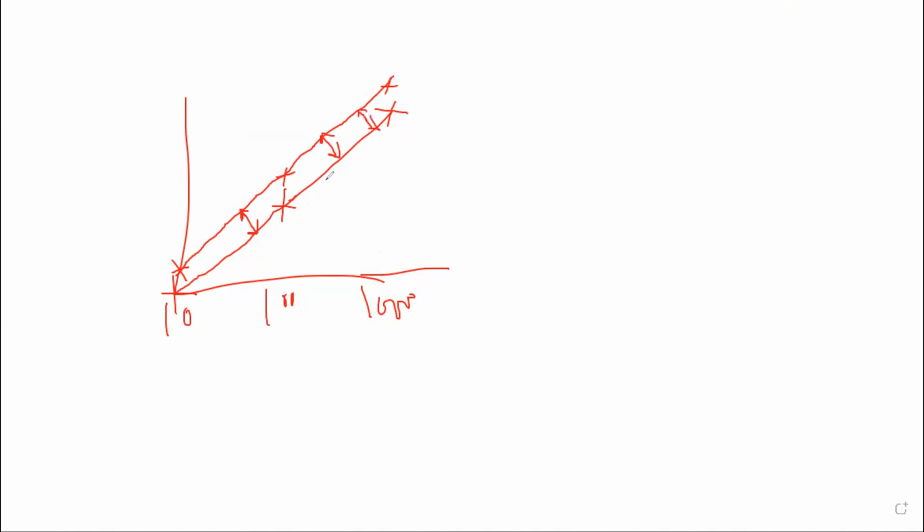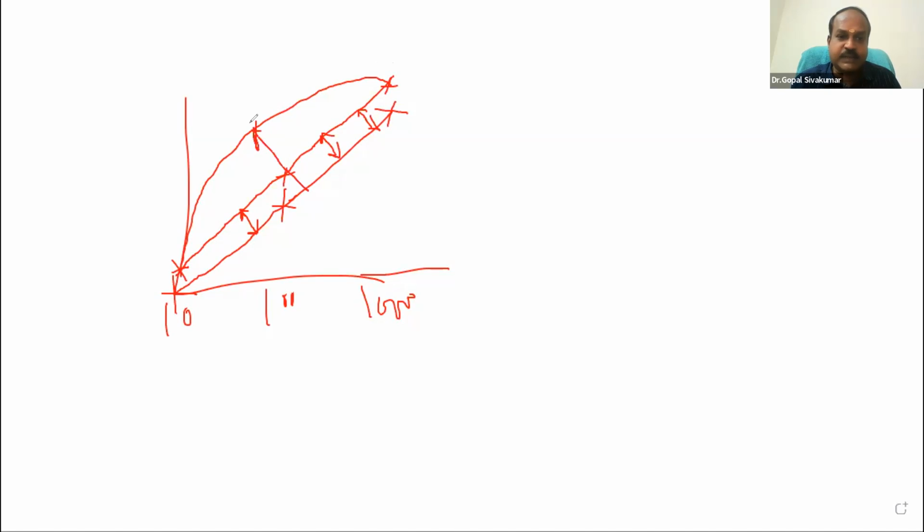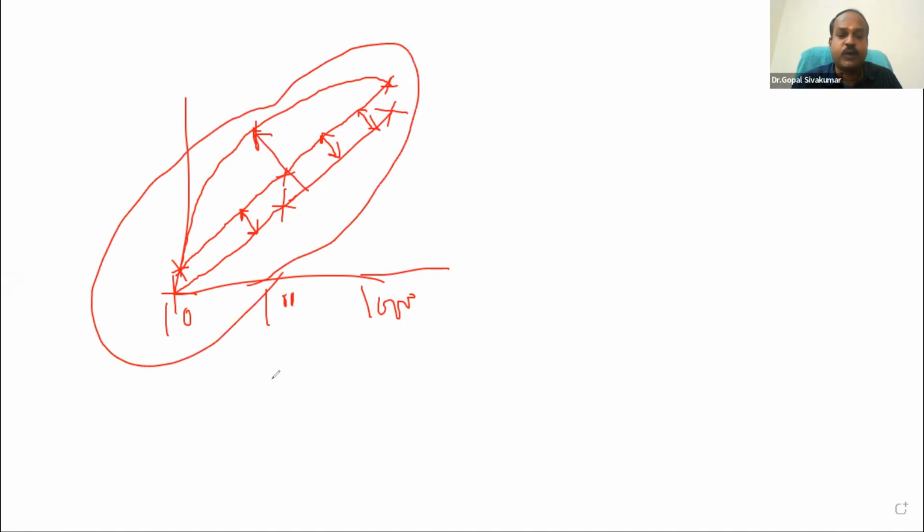Suppose while measuring 100, bias has become 120. Now my reading is going like this. Now at the center, the bias is too much. This is generally not preferred. Bias should be constant. Bias should be linear. Bias should be stable. Right? You should know how your measurement system is behaving within the range. This knowledge is important if you want to create a calibration table. Otherwise, no problem.